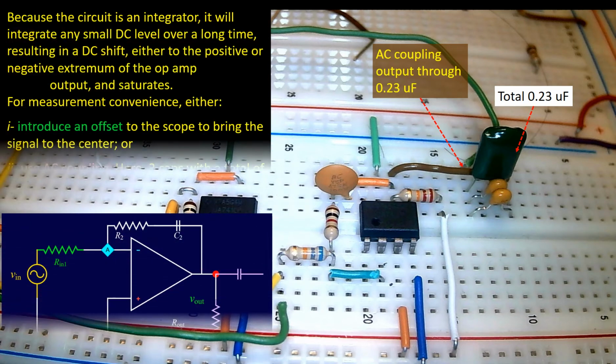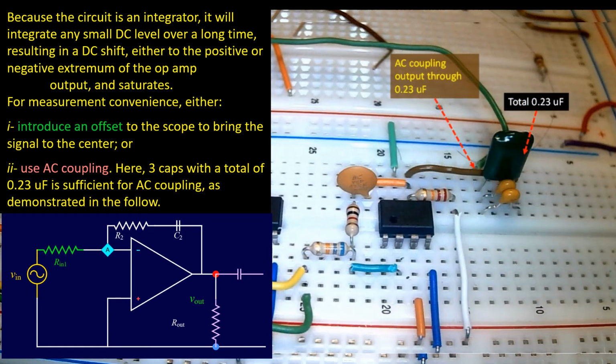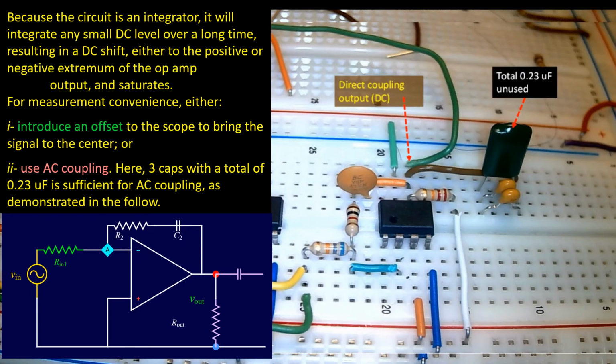This photograph illustrates the RC circuit discussed above. A set of 3 capacitors are added together for 0.23 microfarad. The input impedance of the AD2 scope is likely in the megaohm range, and it appeared that 0.23 microfarad is adequate for tasks C2 and C3. The wire connected to scope channel 2 could be moved back and forth as shown in the video to ensure no observable distortion of the AC output of the integrator, while the DC drift component was removed.